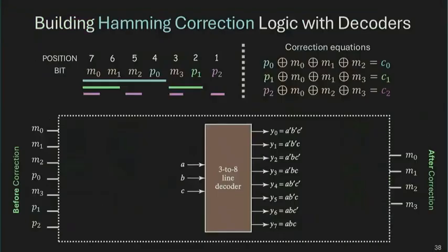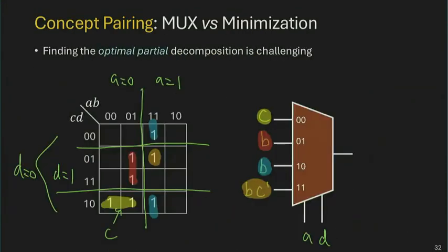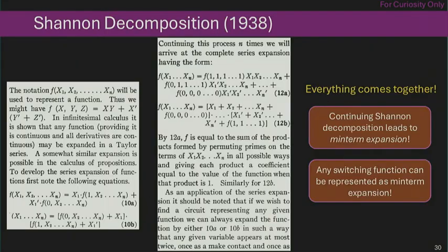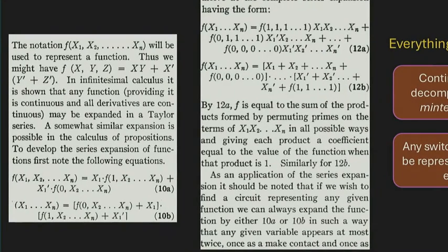So when you build a circuit with a multiplexer, you are essentially doing Shannon decomposition. So when I say cutting the K-map, Shannon decomposition tells you that once you divide by a variable, let's say x1, the rest of the function does not depend on x1. x1 is set to a constant, which simplifies the function, and then you implement it with the remaining variables.